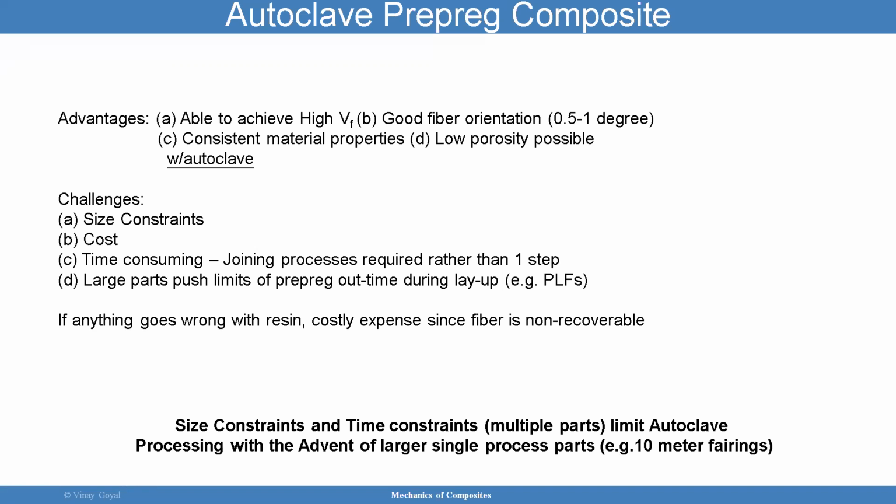If anything goes wrong with resin, you know, that's a costly expense. Since the fiber is non-recoverable, that can be an issue. So size constraints and time constraints can limit the autoclave processing with the advent of larger and larger parts that you may see.